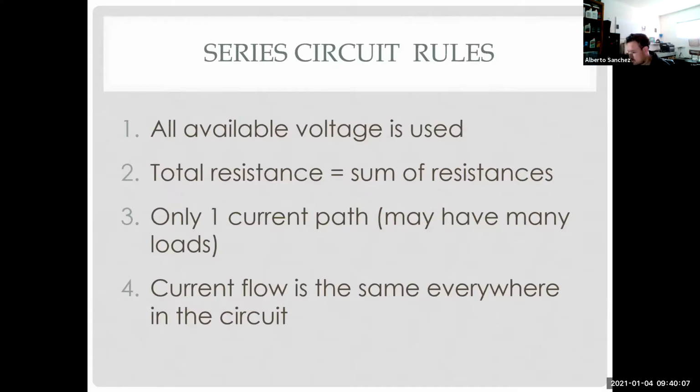I like it. And here's another key one. Because there's only one current path, current flow is the same everywhere in the circuit. So no matter where I test it, it's the same. So whether I test it on the positive side or the negative side, whether I test it closer to the battery or closer to the load, as long as it's a series circuit, that current's going to be the same everywhere. That allows me to do testing at the easiest test point, at the easiest place to do it.